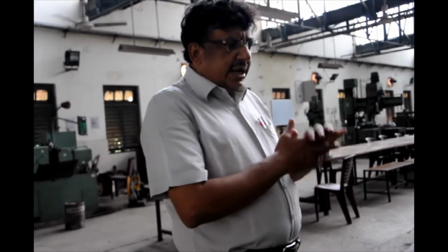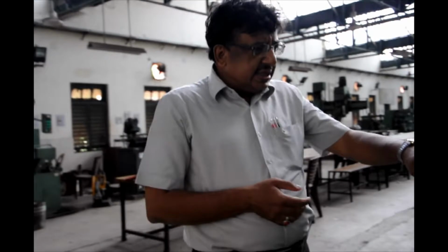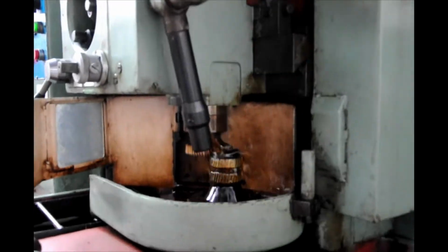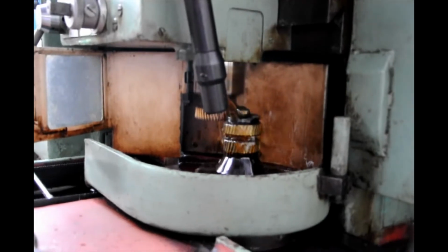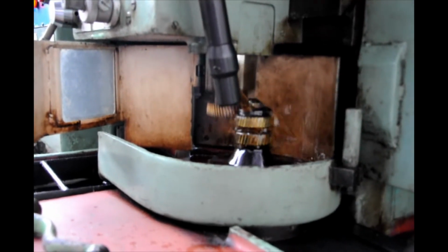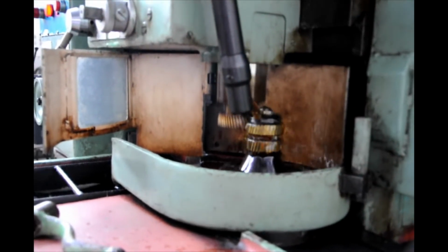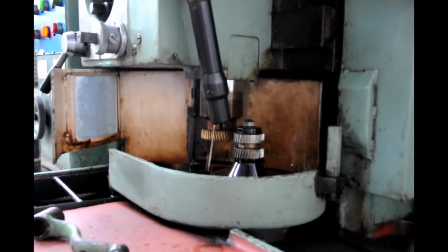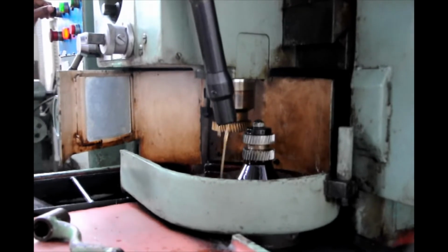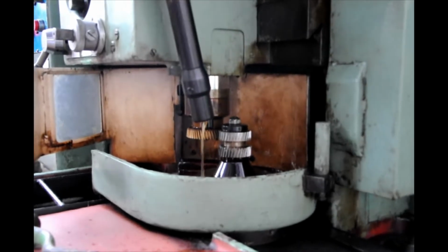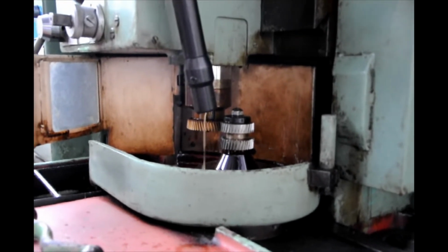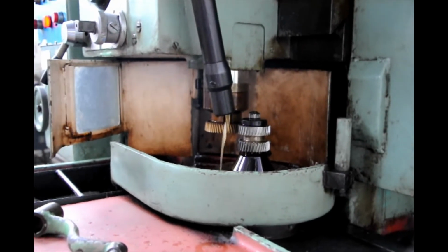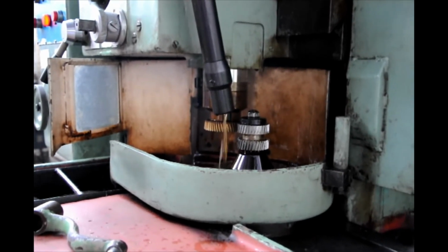So this is a typical type of machine, and these cutting fluids based on oils are there because huge amount of heat and other things are generated, and this oil is sticking to the surfaces of all those cut gears so that less amount of wear and tear and other things will take place. So these kind of lubrications and other things are absolutely important, and one can easily find out how the cutters and other things and gear profiles are cut.